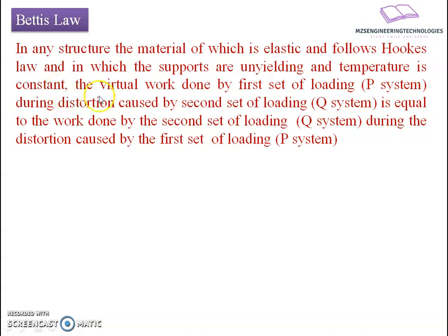Then in that case, the virtual work done by the first set of loading, let us say the P system is that first load system, due to distortion caused by the second load system, the Q system, is equal to, if I reverse the situation, work done by the Q system and distortion caused by the P system, that is the first loading set. So what will happen? The virtual work done by both the systems will be equal.